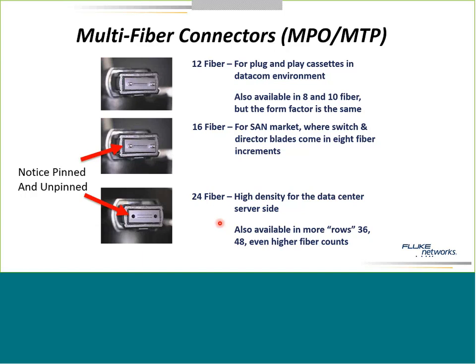Now, if we had multiple wavelengths available on the fiber, we could transmit at 10 gigabits on each one of those wavelengths. It's one of the tricks of single mode fiber. Really, we don't know how many wavelengths are available to us yet, and every time we get a new one, we can put another 10 gigabits on it. And the other option for accelerating our speed is to transmit in parallel multiple 10 gigabit links.